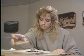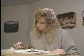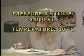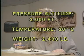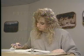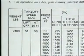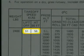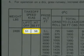For this example, let's assume the following conditions exist. The pressure altitude is 3,000 feet. The temperature is 20 degrees Celsius. And the airplane is at its maximum takeoff weight of 2,400 pounds. The table lists the appropriate airspeeds for liftoff as well as the recommended speed once you're 50 feet off the ground. These airspeeds help to assure that the airplane will perform as shown.